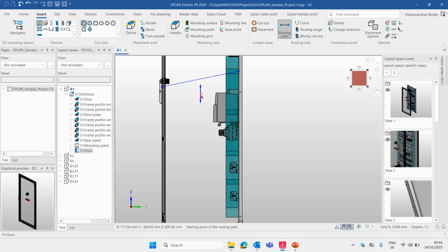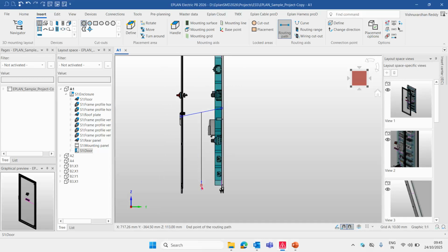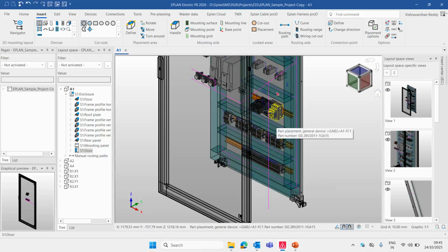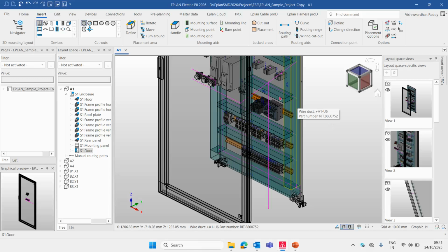Now I'll drag that line. Oh, did I make a mistake? Yeah, one click I should have done. So once you press enter, then you have to do it and then you drag that mouse. You see that automatically you can draw the line to whichever extent you want to create it. And then I will left click. After that I'll hit space bar. Now I want to cross check whether that line is a straight line. You can see that automatically this particular line shows a straight line over here. So this is very, very important. So once I get the straight line, now I can go back to that U curve.